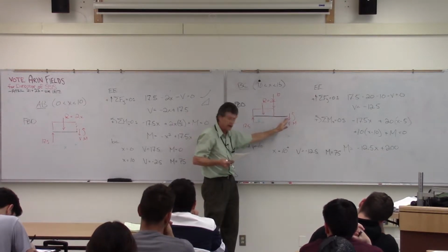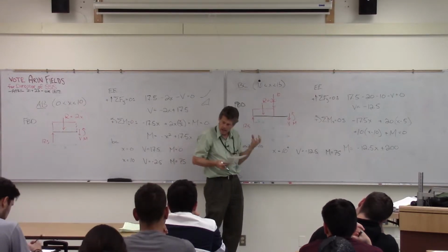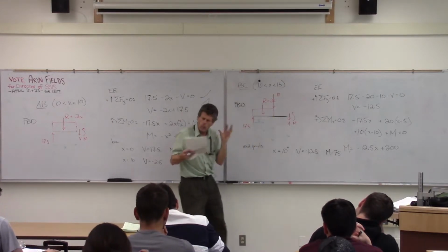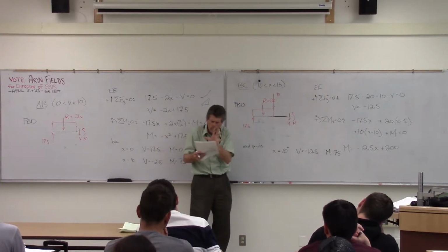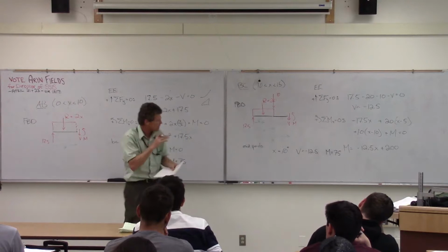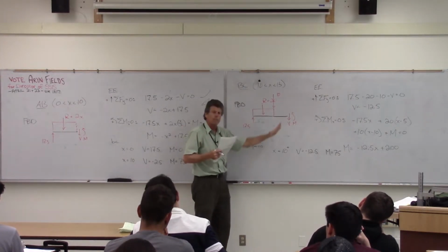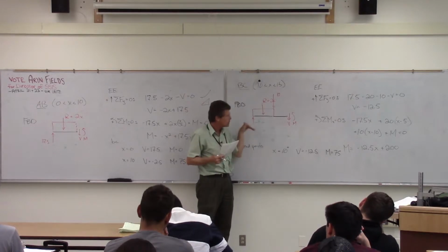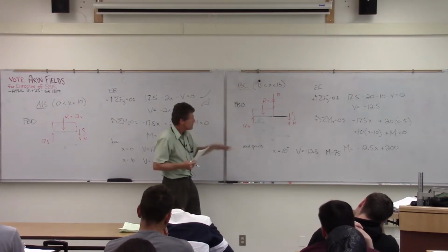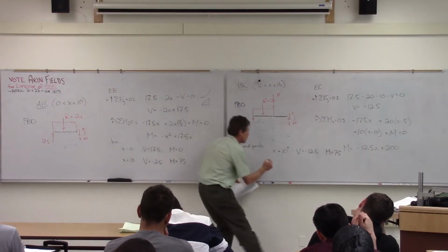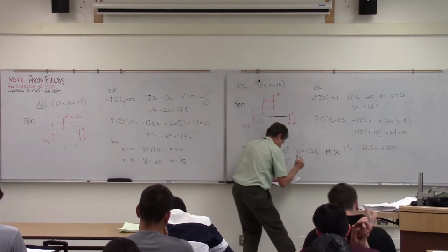Now, yeah, it'll start picking up as I move away, but when I make a cut very close to that 10-foot level there, the moment shouldn't change. And in terms of the beam, that makes sense. It's a continuous beam, so we're not going to see any sort of changes there. Moment's basically describing how it deflects, and we're not going to see any kinks there. So that makes sense, and then what we'll want to do is take it to x 15 and just short of that.